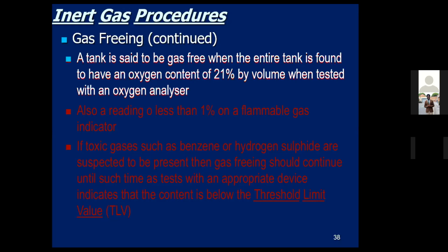We have different portable gas equipment. We have the Riken Kaiki, we have the MSA Altair, we have different equipment that measure different components of gases, and you have to be very, very careful. Some of these measure in percentage LEL, which is lower explosive limit, and some of the instruments measure upper explosive limit. Some of them measure in percentage volume. So you have to be extraordinarily careful when using this.